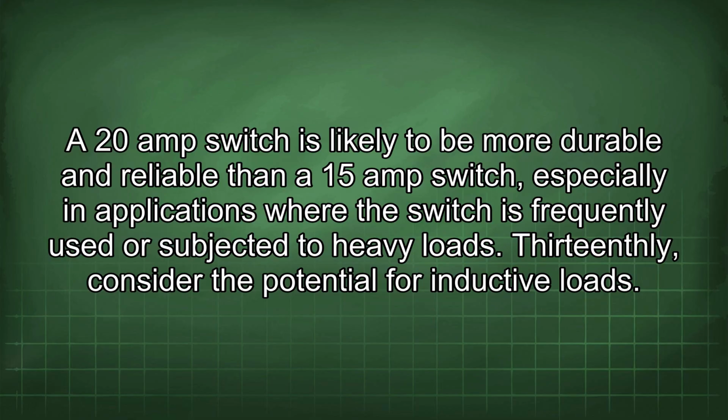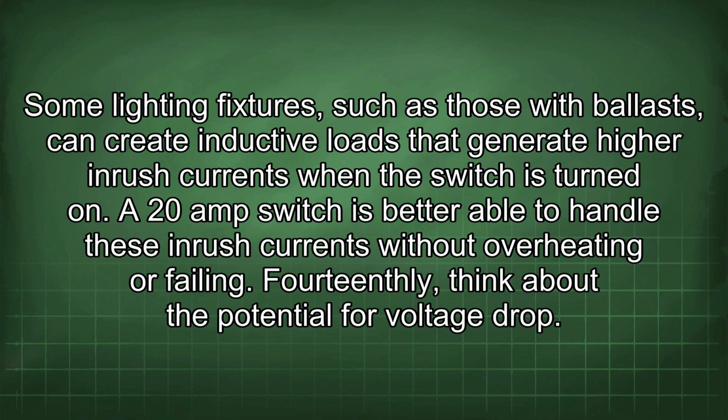13thly, consider the potential for inductive loads. Some lighting fixtures, such as those with ballasts, can create inductive loads that generate higher inrush currents when the switch is turned on. A 20 amp switch is better able to handle these inrush currents without overheating or failing.